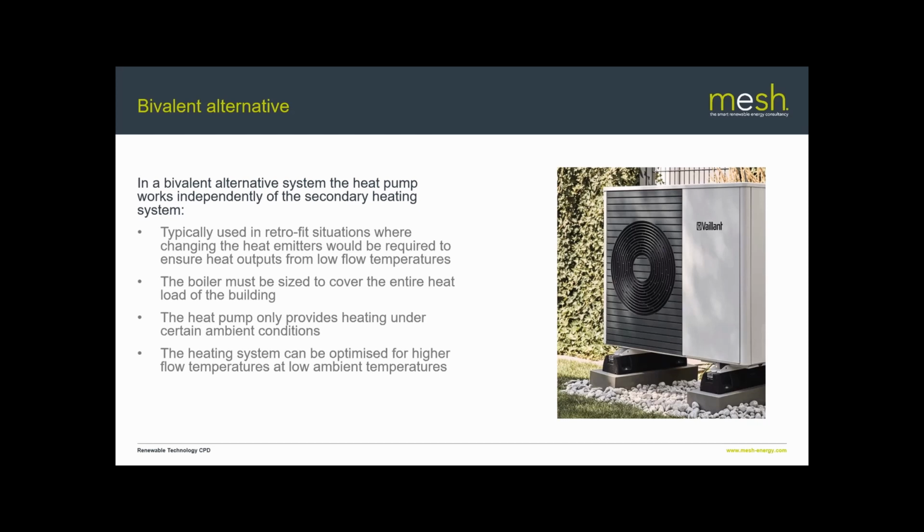So the main reason for this is to give you higher flow temperatures. That's really the long and the short of it. That's why you'd use a bivalent alternative system. That's probably the biggest single reason for doing it.